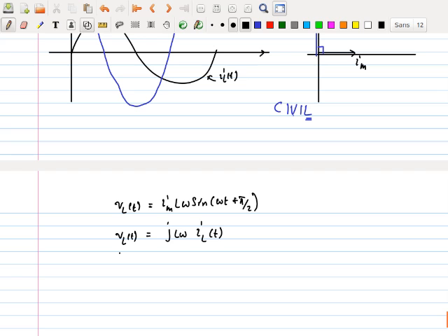Now again, let's look at this. This looks like Ohm's law. This is V, this is going to be I, and that looks like a resistance. But jL omega, you realize, is a complex number, hence we can't call it a resistance, so we call this the reactance. Right? Call it the reactance.